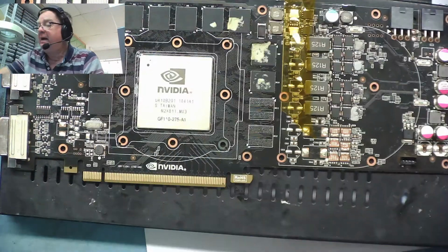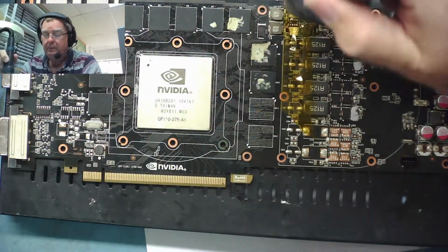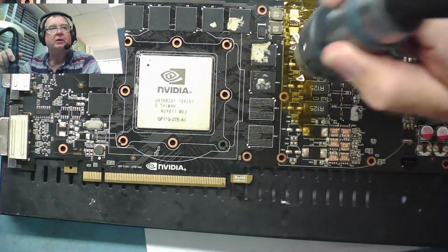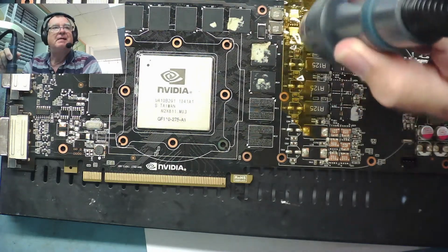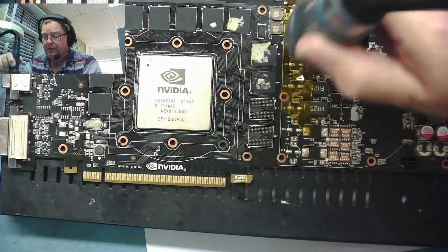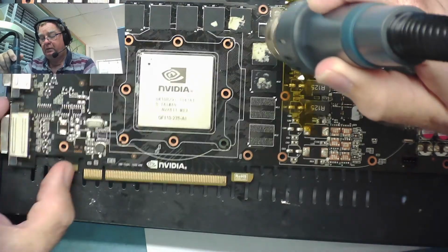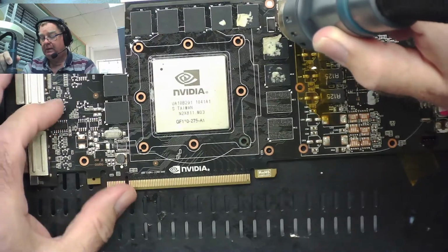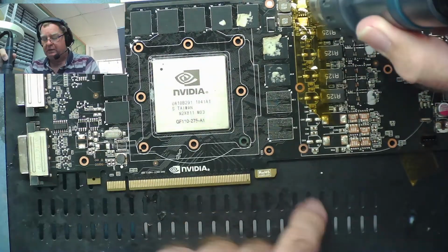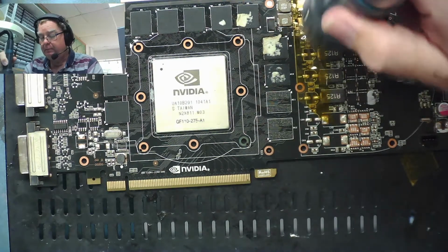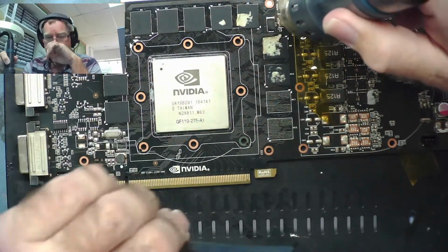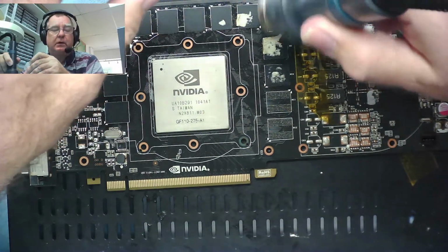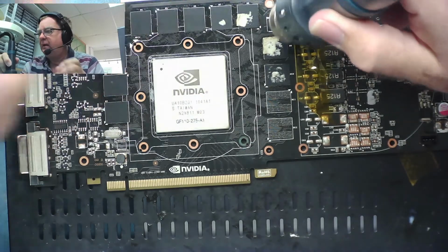So 450 again, maximum airflow. We don't want to stress the boards, so we're not going to get heat directly on these straight away. We're just going to get the general area warming up. This might actually help if I just balance the end of the coils slightly off here, so I'm reducing the conduction into this metal. Start to get some more heat into it now. Right, I've warmed it up a bit.